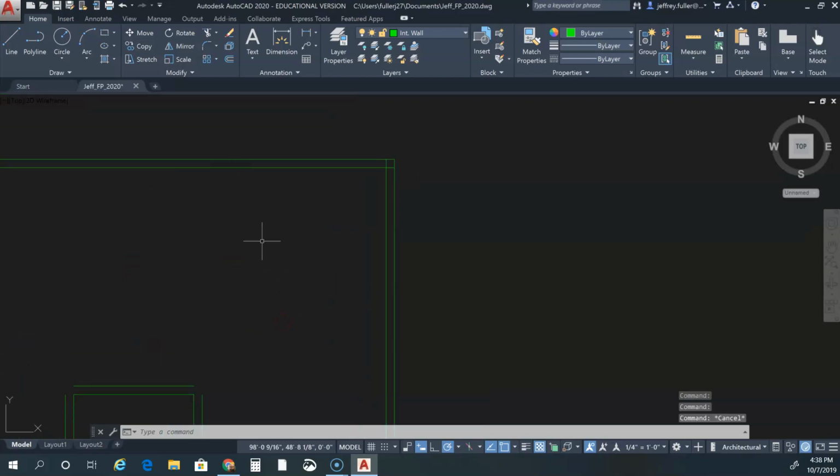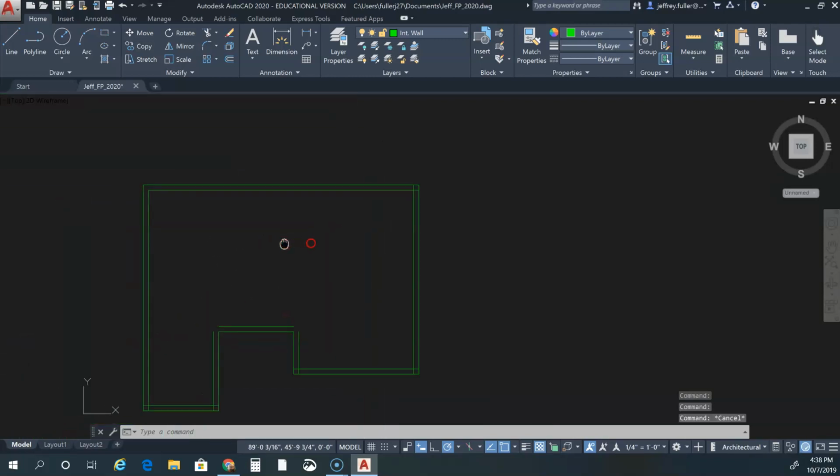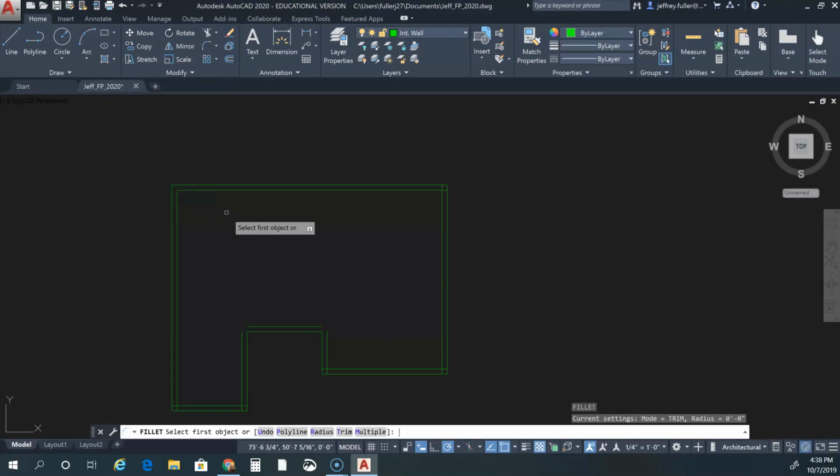Whoops. Okay, I forgot one other thing too. To redo that, every time you click to do a corner, with this particular tool and with some of the other tools as well, it doesn't stay in that tool. You have to either click up here again or do the easy thing, which is click the enter button on your keyboard. So after doing one corner, I'll click the enter button on my keyboard and it'll go back into that most recent tool.